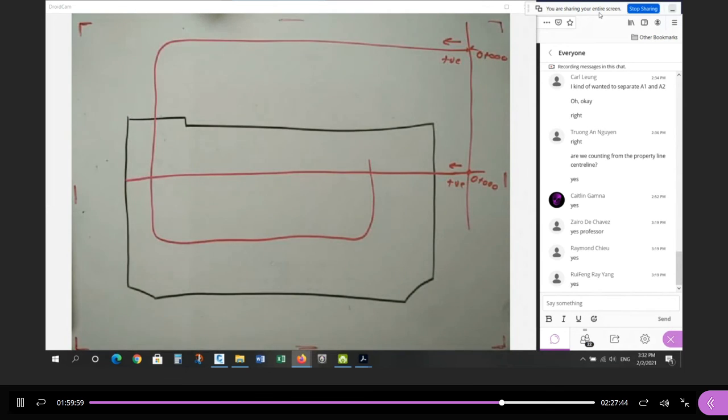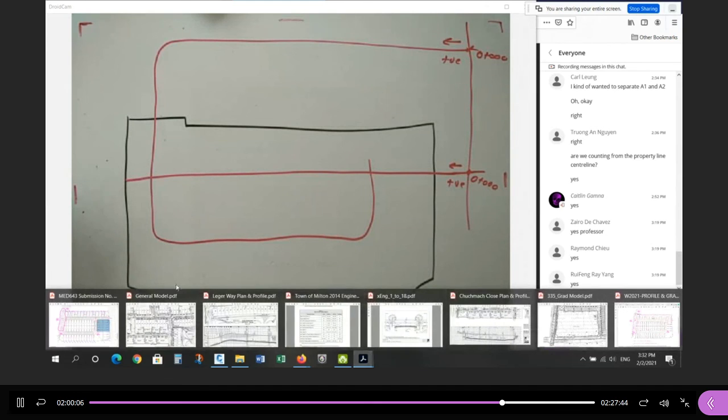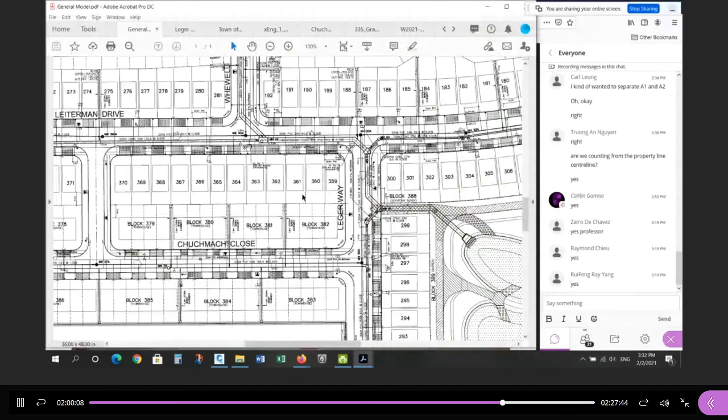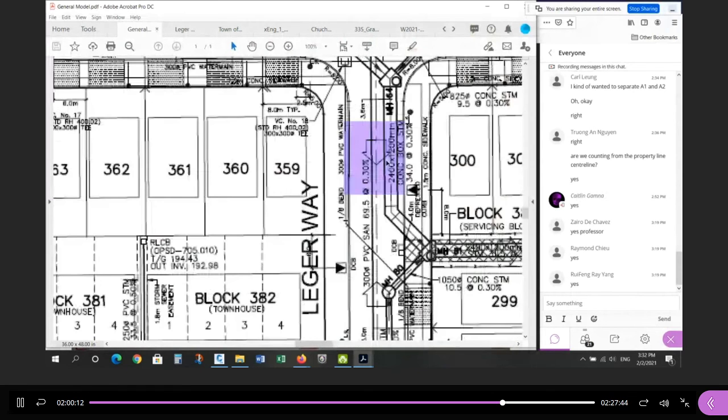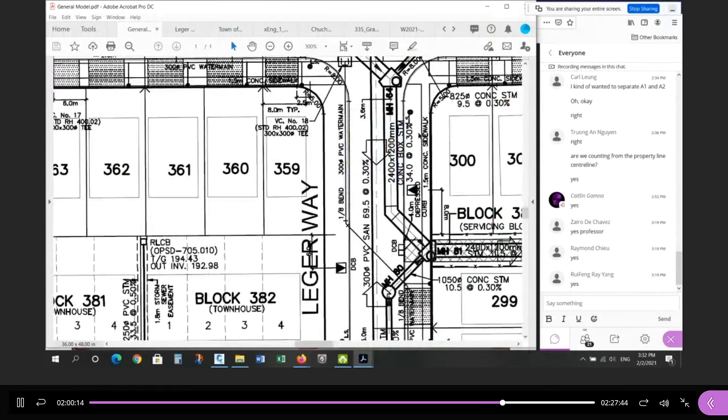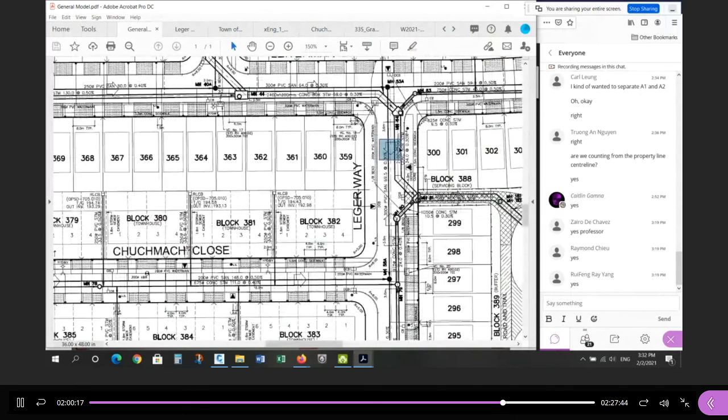So you have to flow along the gutters and take the water to the pond in this case. If we go to here, let's just do a quick overview. If we go to the site, you'll notice all the overland flow, these big fat arrows. If the sewers are full, this is the slope of the road. Now the actual gradient, 2%, 3%, 5%, doesn't matter, but it is pointing downhill.